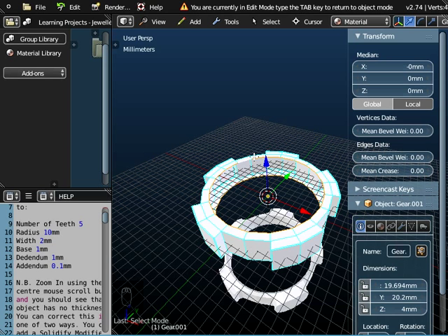Now what I'm going to do is to add faces between this. Now we do recommend that you use the FluidDesigner menu, which is this menu system here, for beginners learning how to do 3D printing. But you should be aware also that FluidDesigner behind the background is Blender. And the command that we want to use next is actually a Blender command that doesn't appear on FluidDesigner. So we need to change this menu system from FluidDesigner to Blender.